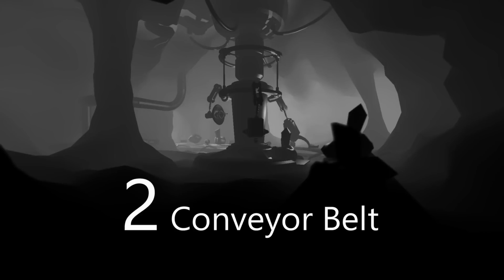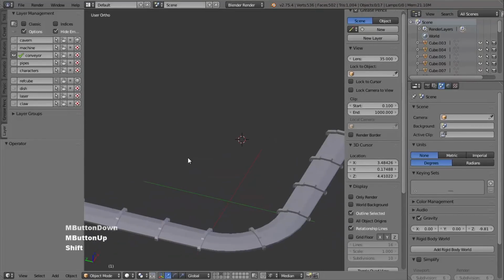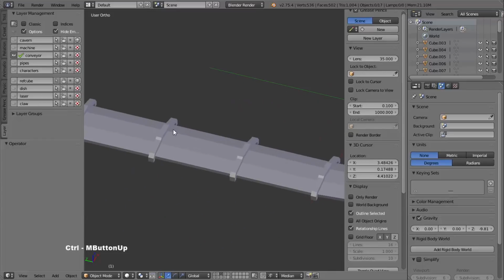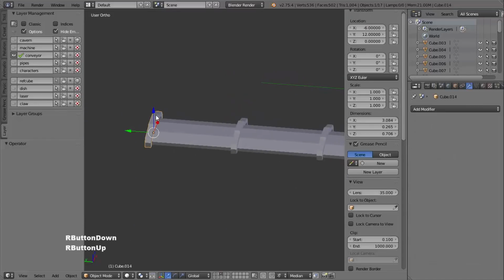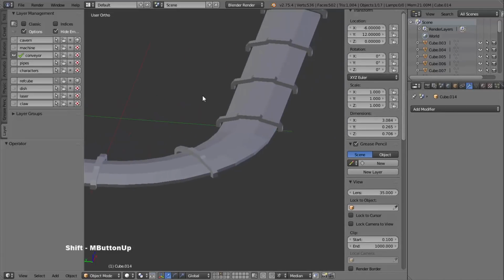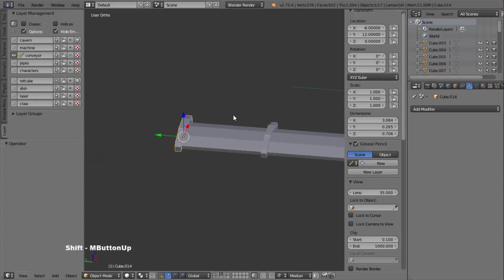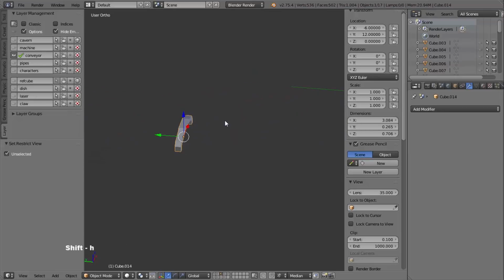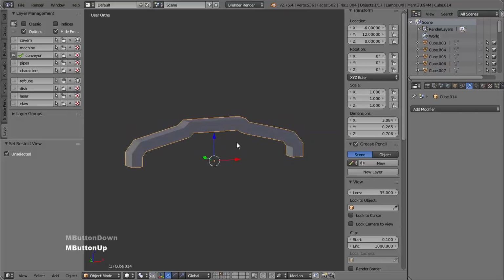So moving on then, I want to show the layer with the conveyor sections on it, and I'm going to hide the pipes, and I'm going to use this similar method of sharing data across objects to work on these different sections. So I'm going to make some changes to one of these segments and later on share that data across all of them. So I'm going to hide everything else for now. I'm going to press Shift and H and then press my decimal point key to focus on this object.